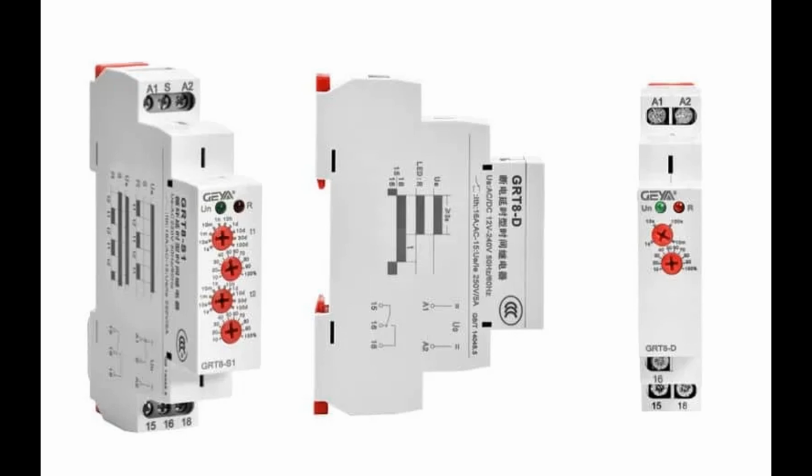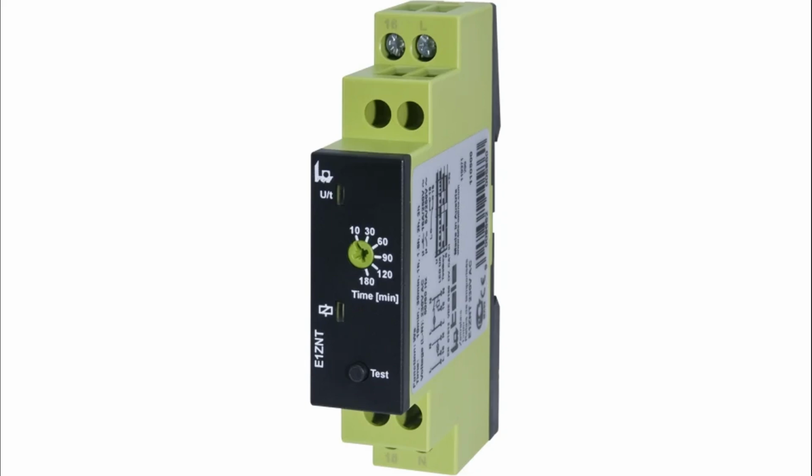Recycling delay. Recycling delay relays continuously cycle through a predetermined delay period, repeatedly activating and deactivating the load in a repetitive manner. After the control input triggers the relay, there is a delay before the contacts switch to the energized state, activating the load. Once the delay period elapses, the contacts revert to their initial state, deactivating the load, and the cycle repeats. These types of delays cater to different application requirements where precise timing control is necessary.